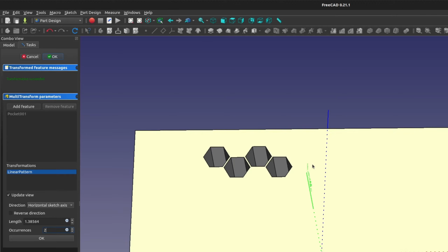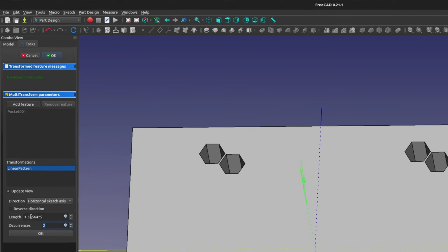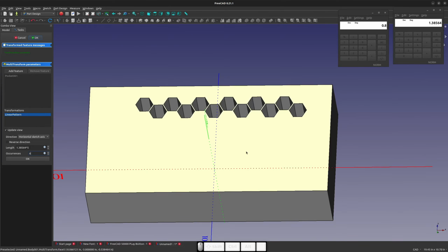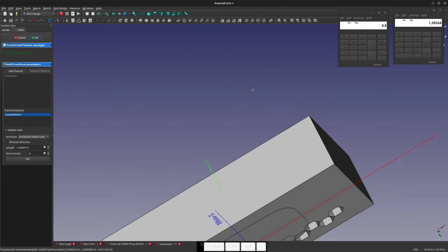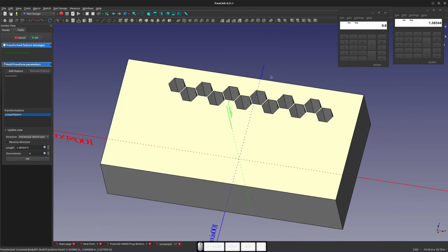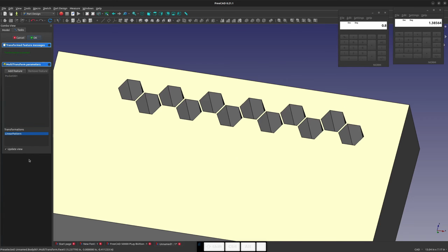but now I want to go all the way across, evenly spaced, and to do that, I'm going to just say my length, times 5 over. Excellent. And then I'm going to do my occurrences one more than the number I just typed, so we're going to say 6 occurrences. And there we have an evenly spaced one. And you can tell the pattern is enveloping our entire play button, which is my intent there. Next, we say OK to that.